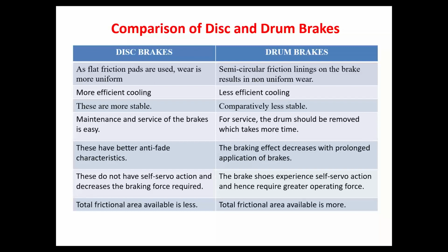If you go to any areas where there are water-prone roads, your vehicle will not be stable, but such issues will not be there in the disc brake. Whenever water falls onto the disc, immediately it will be wiped off automatically, because it's a flat surface. But if you consider the drum brakes, water can get locked between the drum and the brake pad.